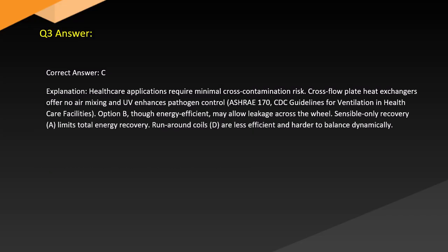Answer. Correct answer: C. Explanation. Healthcare applications require minimal cross-contamination risk. Cross-flow plate heat exchangers offer no air mixing, and UV enhances pathogen control, per ASHRAE 170 and CDC guidelines for ventilation in healthcare facilities. Option B, though energy efficient, may allow leakage across the wheel. Sensible-only recovery, A, limits total energy recovery. Run-around coils, D, are less efficient and harder to balance dynamically.